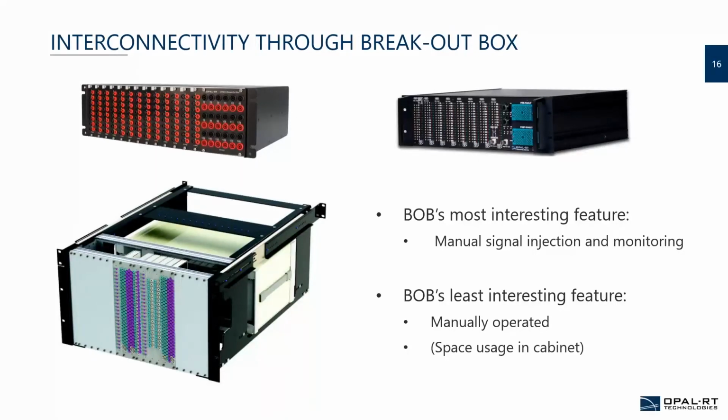Or you want to just probe what's going on in the signals. You're sending signals, let's say temperatures, and the temperature has an offset of 10 degrees in the reading of the controller. What's going on? You want to demystify where the problem is. Is it the signals that are not good? Maybe the test bench doesn't produce the right signal, so you know what you're expecting.